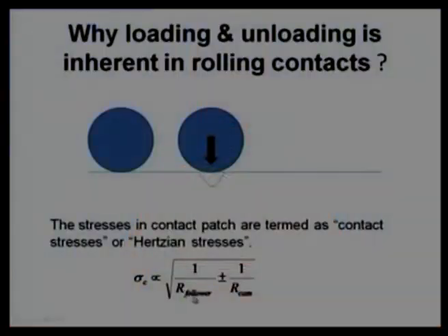But what is the interesting point which we can gain from this is that as the radius is increasing, contact stresses will go down, will reduce. Similarly, if the cam radius is increasing and if it is convex, then we can say again contact stresses will be reduced. However, if there is a concave and convex combination, then the overall combination will give lesser results.